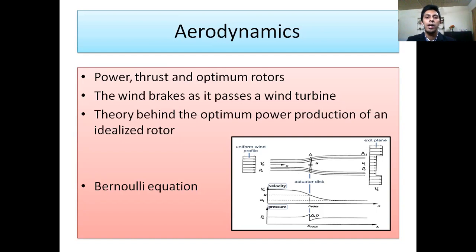Now, by subtracting the equations, we can derive an expression for delta P. Here is the expression for delta P from P naught. We can also utilize mass conservation, because rho A1 U1 equals rho A U, and this gives 59% of the incoming kinetic energy.